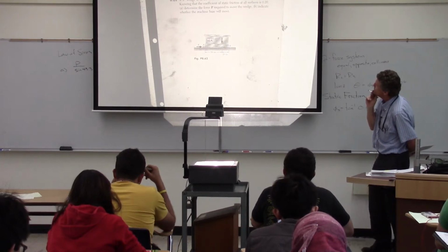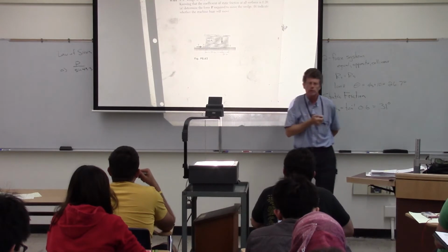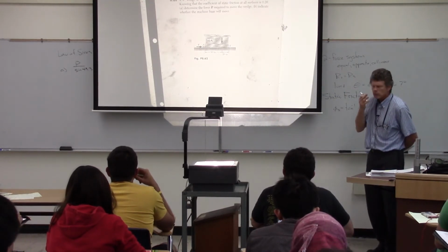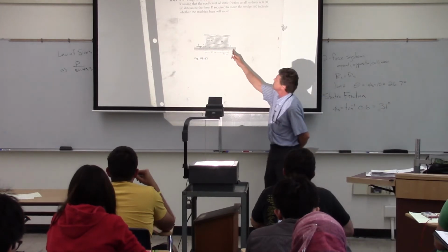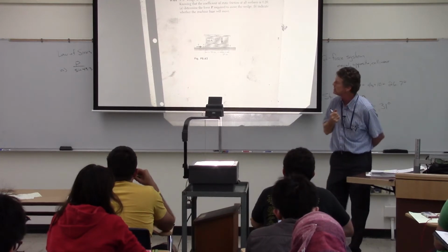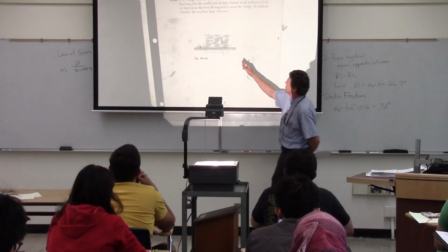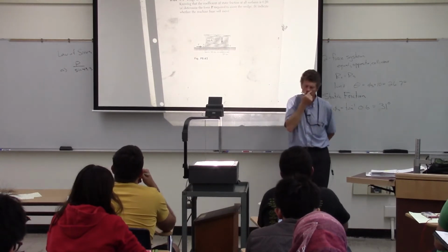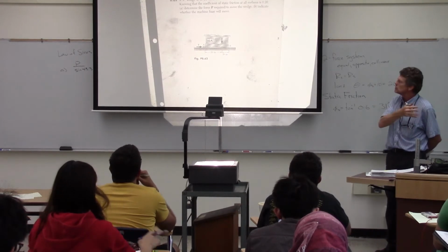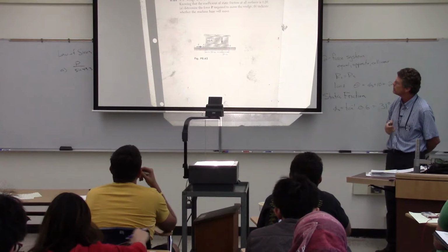And then the other question is we've got this issue here at B. Again, it's not glued to the ground. There's nothing holding it there, so there's friction there. Now, interesting point, it's a very small area, but remember, friction is independent of the area that's in contact. So we've got this small area of contact there, but again, we need to find out whether we have enough friction there so when we start pushing that 5-degree wedge under there, the whole machine doesn't start going off horizontally.